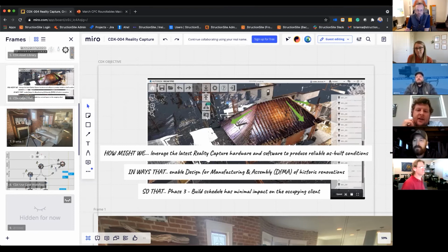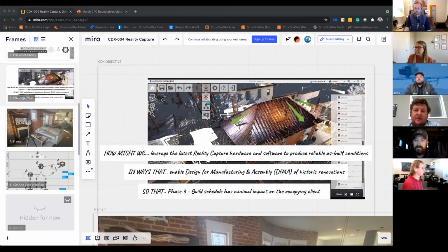Yeah. And I think, speaking from a wood window perspective, or if we do a prefabricated dormer system, kind of like we explored, we can build understanding that wood can be planed down. There are certain things at that point that the dormer, as it integrates with the roof system, is going to have some kind of flashing up to it or something like that. So in certain areas, the tolerance is not going to really be that.